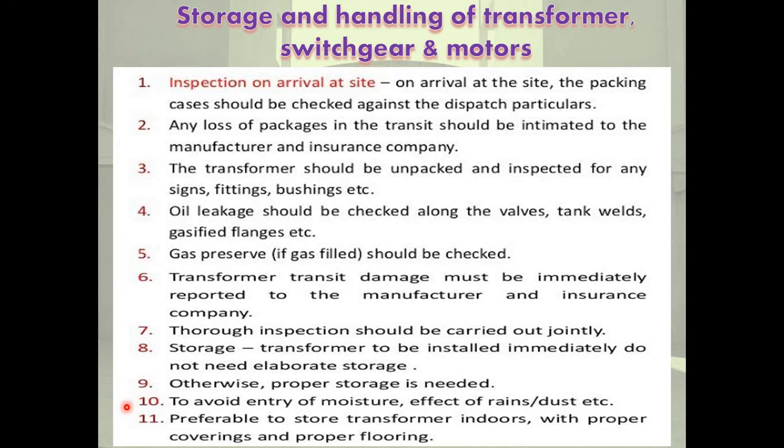The total installation comprises the following essential features: a foundation made of cement concrete, bed plate, and foundation bolt. In concrete foundations, the machines with or without bed plate should be securely bolted to solid, level foundations. The foundation may be common for motor and generator, or for motor and the driven machines. Then the qualities of a good foundation are rigidity and freedom from vibrations.